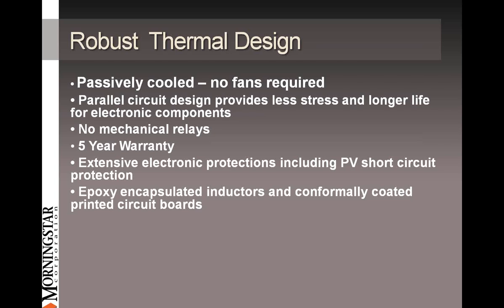This controller, the 45 and the 60, they're not just a giant 45 or 60 amp controller. The 45 is actually two 22 amp controllers, 22 and a half to be exact, and the 60 amp is three 20 amp controllers built inside. The reason that's important is because, like a gear system in a car, we're able to turn on and off or basically shift gears depending on the amount of power we're working with.